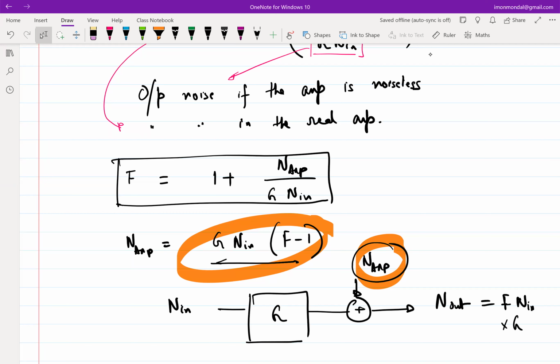Right, so the moment you have something as infinite, your block will obviously add some noise. It will never have 0 noise. It will add some noise, which means you have finite SNR at the output. Input infinite SNR, finite SNR output, the ratio will become infinite, right? So this noise factor definition breaks down when you do not consider input noise, but that never is the case.